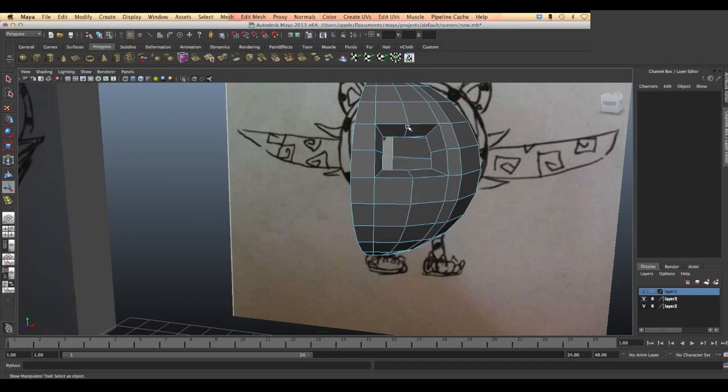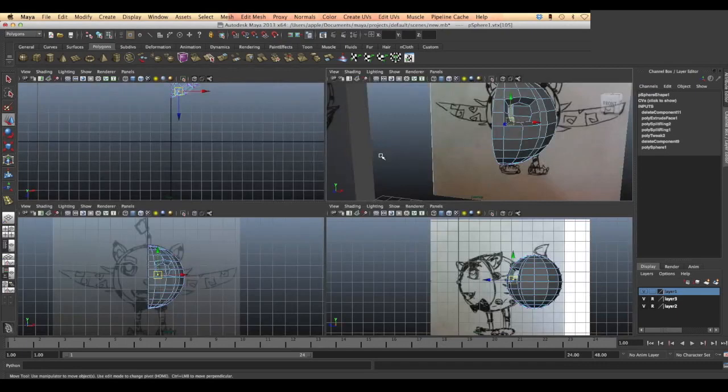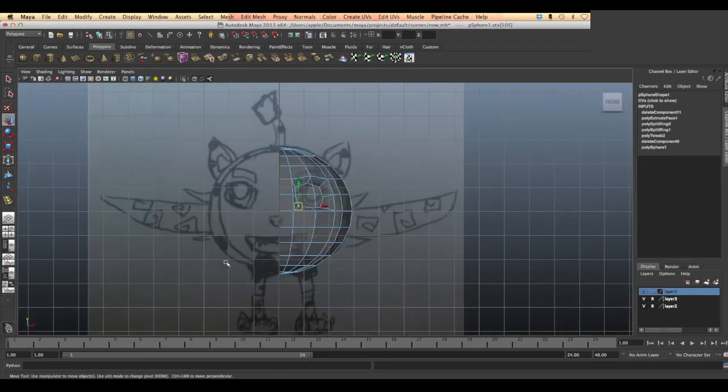We will go to the vertex mode and then select the move tool. The vertex mode enables you to select the intersection points created from the lines or the edges. So now I'm adjusting the vertex points. I'm going to the front view so I can take a good look at how the eye hole is shaped compared with my reference image.